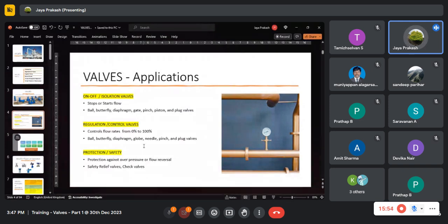So even our pressure cooker has a safety valve. You know the weight on top of the pressure cooker, where the cooker is being used for cooking rice or something like that. That weight is calibrated depending upon the maximum pressure that the vessel can tolerate. When it reaches that level, the weight will go up and release the excess pressure. That is also a type of valve.